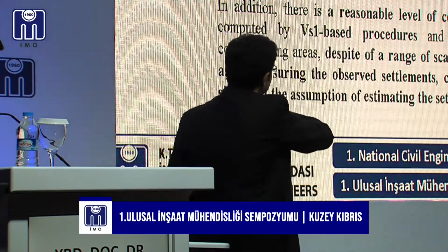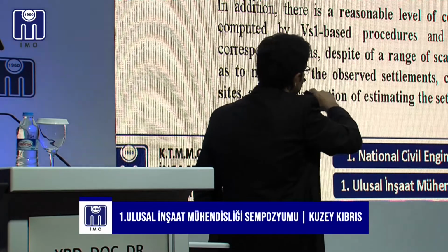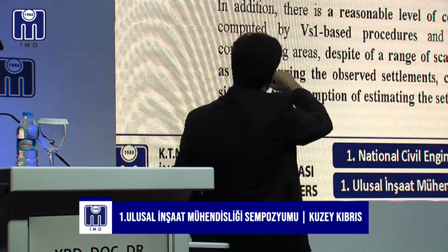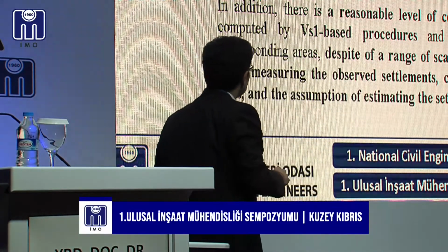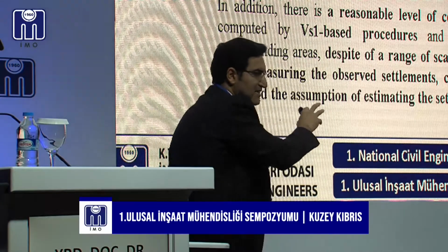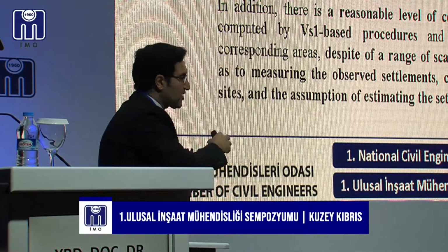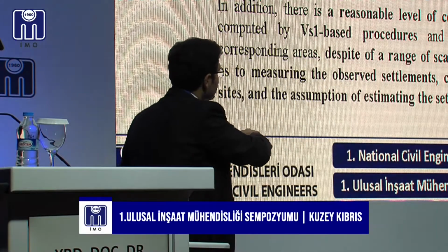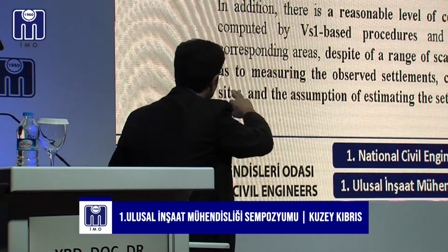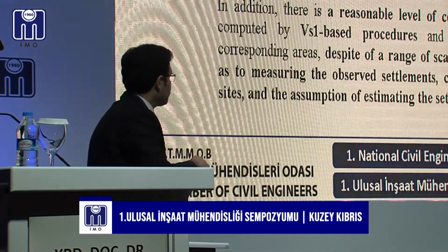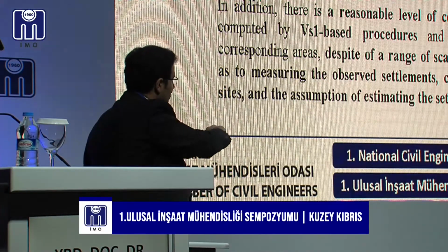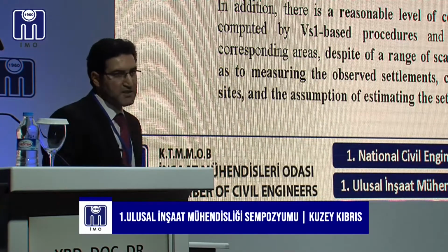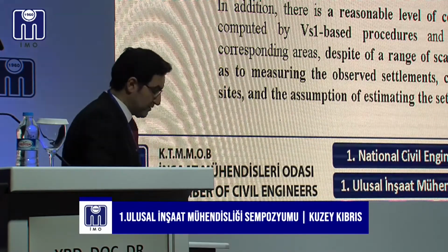Thin liquefiable soil layers are particularly impossible to detect by the VS-based procedure, so we have to be careful about this drawback. And also, there is a reasonable level of consistency between the settlement computed by the VS-based procedure and the settlement observed in the field.